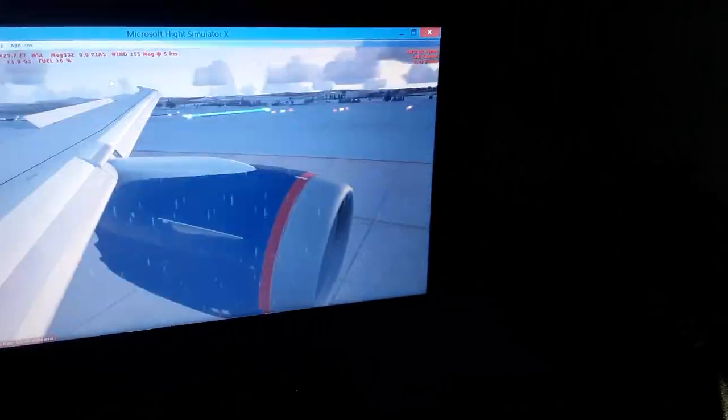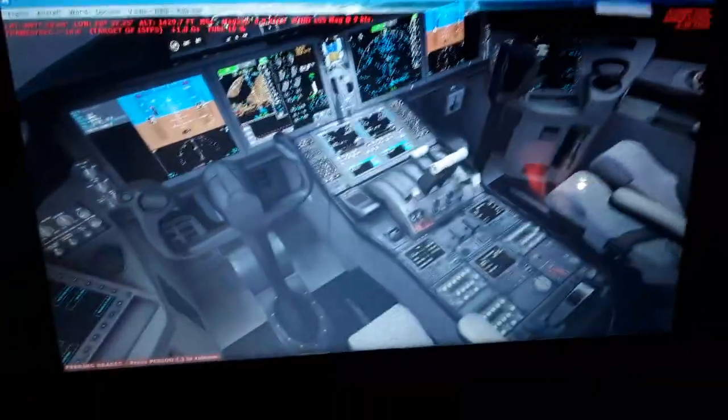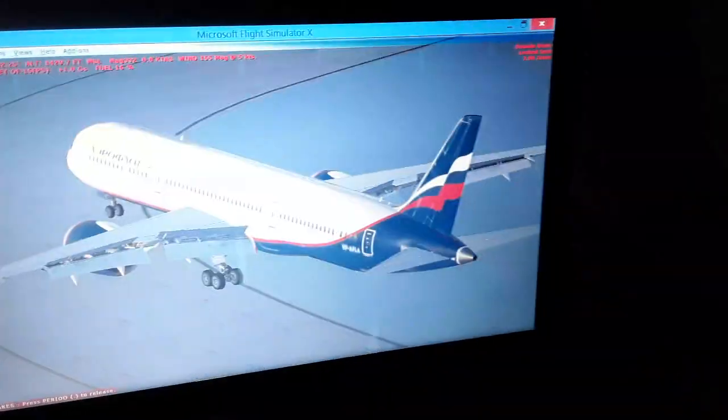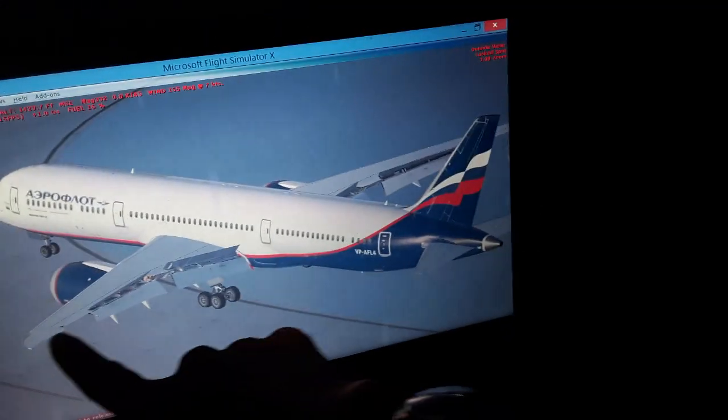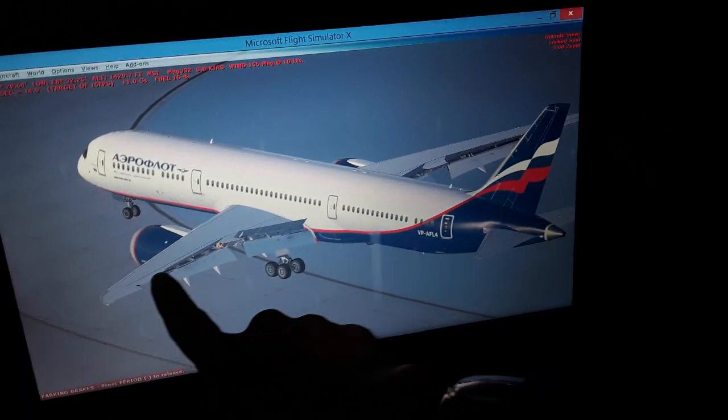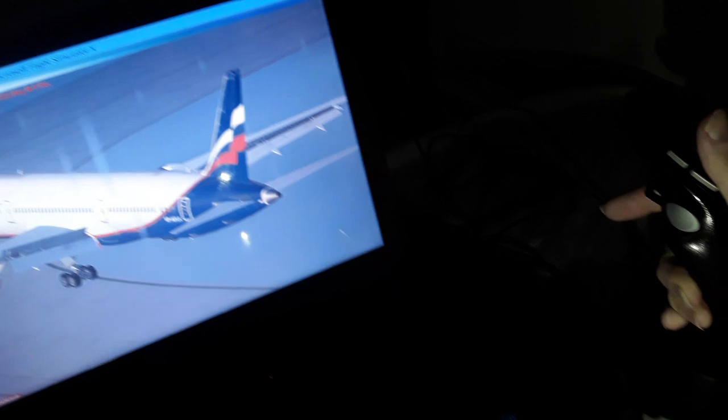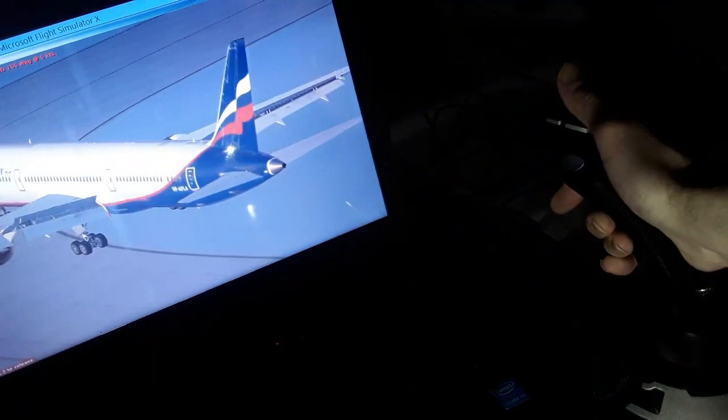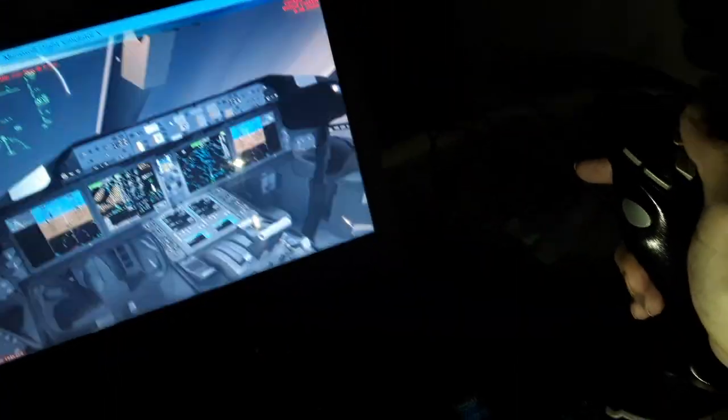So you see the rudders here, rudder pedals. So we have also this axis here from wingtip to wingtip over here. It's the pitch axis. We can use the tail of the aircraft, the horizontal stabilizer over here for climb and descent the aircraft like this. So it's the side stick of the Airbus climb, pull up or pull down, or the yoke as you can see in the Boeing aircraft. So this is the pitch axis. You climb and you descend.